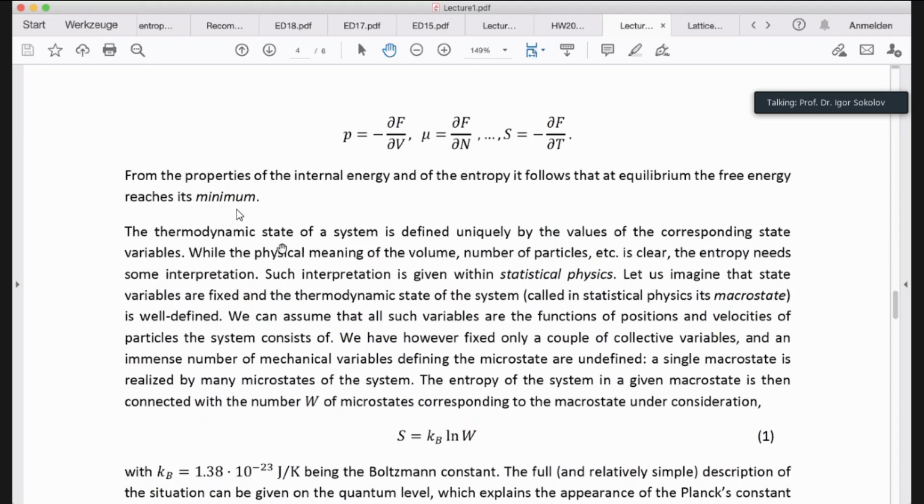Now, the question is, how can one get the equations of state? And here, of course, people can get them experimentally. This one you get by measuring pressure, and this one you get by calorimetric experiments. So you can measure, for example, the heat necessary to change the temperature by 1 degree at different volumes, or if you want at different pressures. Then you recalculate the equation of state from the enthalpy change or whatever you want. So you can get them experimentally.